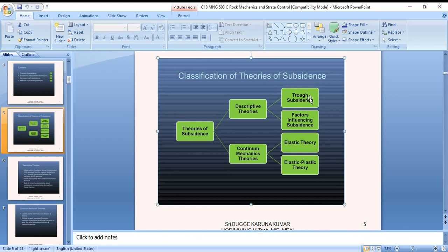From an engineering standpoint, trough subsidence creates two problems: support of the opening and control of the subsurface subsidence during the period of mining, and damage to the surface or structures on the surface. Support of the opening may be affected by leaving unexcavated areas of rock in the form of pillars, or by artificial means such as props or chocks. The treatment of artificial support is not within the scope of this